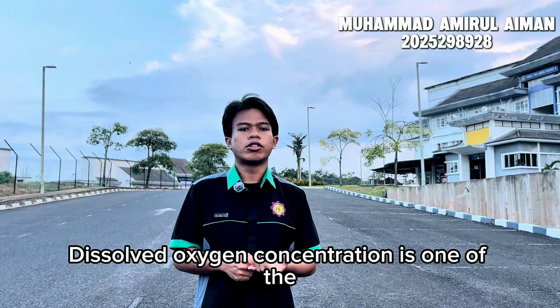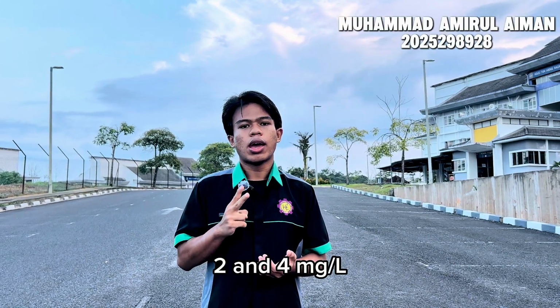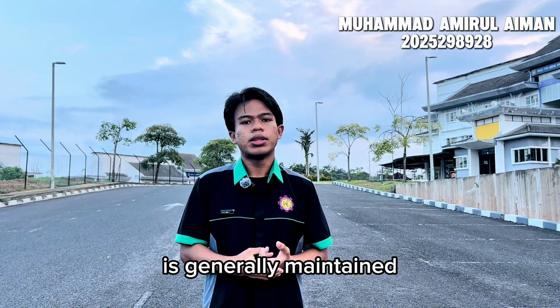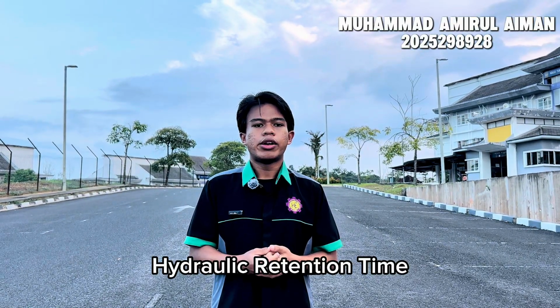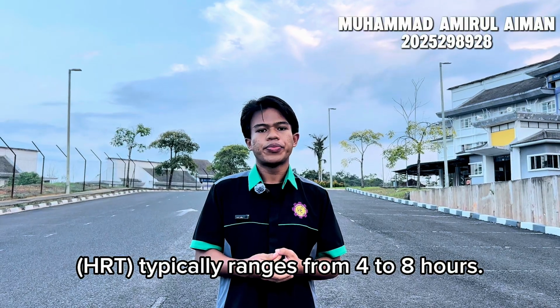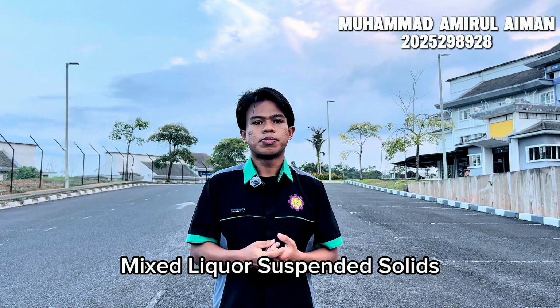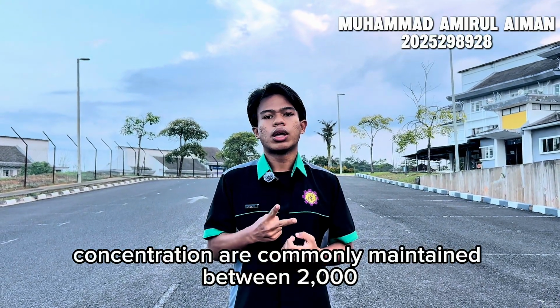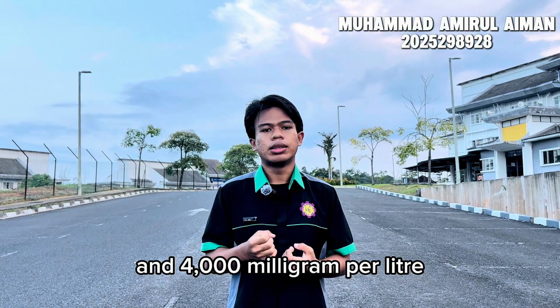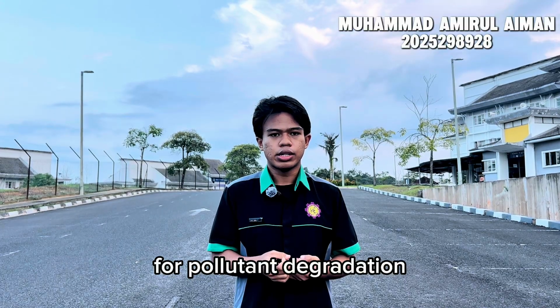Dissolved oxygen concentration is one of the most critical parameters in the process. A dissolved oxygen level between 2 and 4 mg per liter is generally maintained to ensure sufficient oxygen for aerobic microorganisms. Hydraulic retention time (HRT) typically ranges from 4 to 8 hours. Mixed liquor suspended solids (MLSS) concentration is commonly maintained between 2,000 and 4,000 mg per liter to provide an adequate microbial population for pollutant degradation.